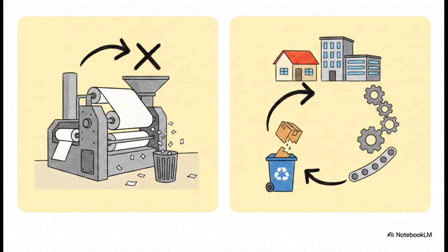But look closely at that parenthetical exclusion, because it's a game changer. You absolutely cannot count rework, regrind, or scrap that is reclaimed within the exact same process that generated it. So if a massive cutting machine trims a paper roll and the loose trimmings fall to the factory floor and are immediately swept up and thrown right back into that same machine's hopper, that is not recycling. That's just basic manufacturing efficiency. The standard does not allow a company to pat itself on the back and label that as recycled content. To count, it has to truly be diverted from a separate, distinct waste stream.